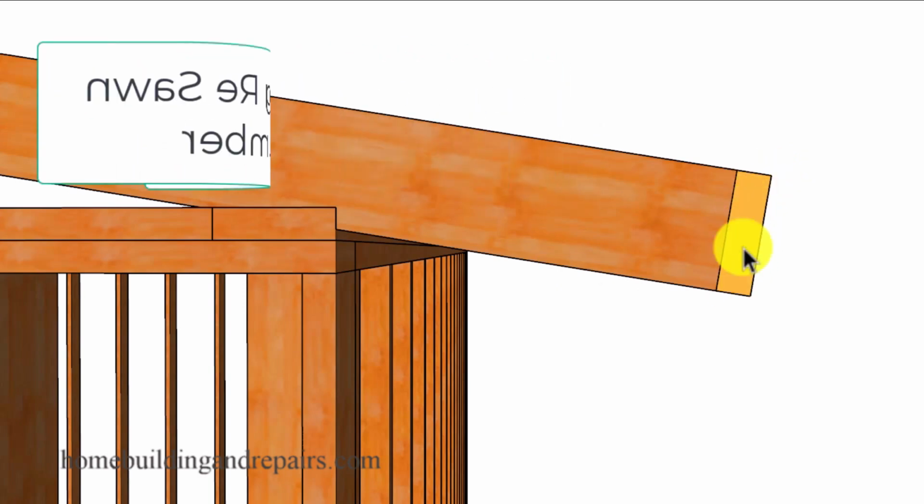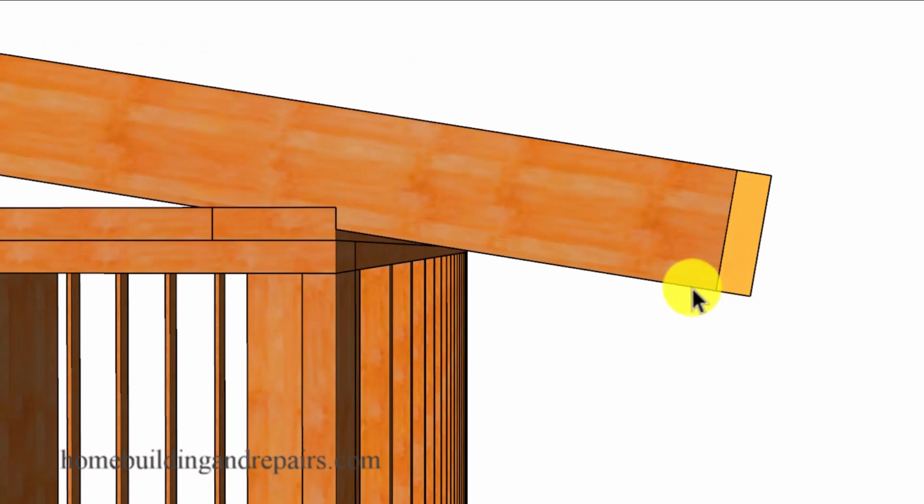And if that was the case, I would either need to lower the fascia board to where it was even at the bottom and then create a problem with the roof sheathing, or raise the fascia board to where it's even with the top of the roof rafter and then have a 1/4 inch gap between the edge of the fascia board and the roof rafter.